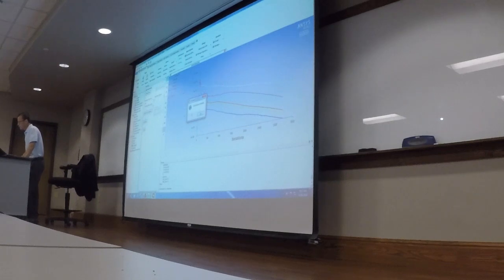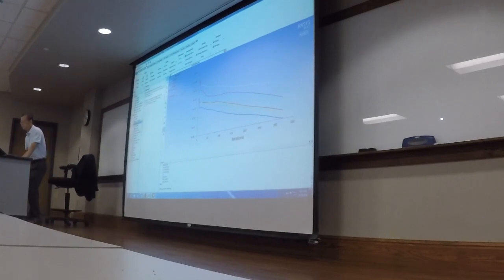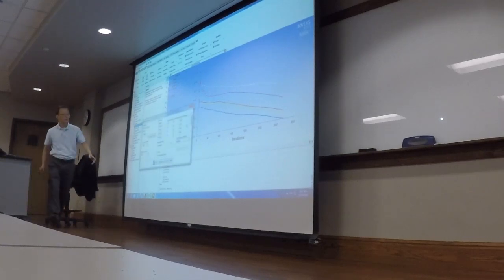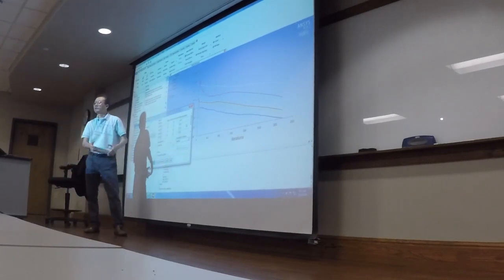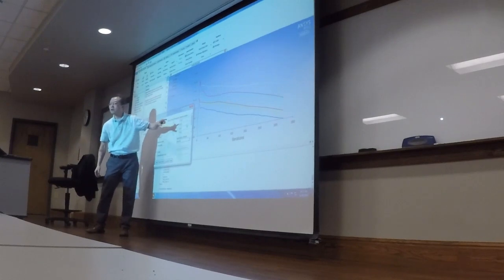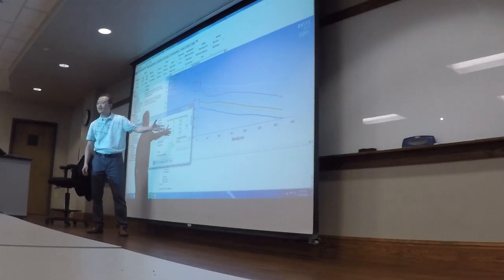All right, it says calculation complete. All right, this is another thing. You see that they're still going down. All the residuals are still going down. So go to monitors. Residuals. And here, these are the default target for this convergence. See, this is 3 order of magnitude reduction. That's the default. And many times it's not enough.